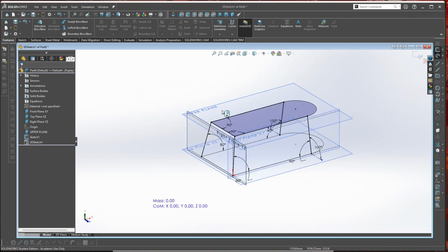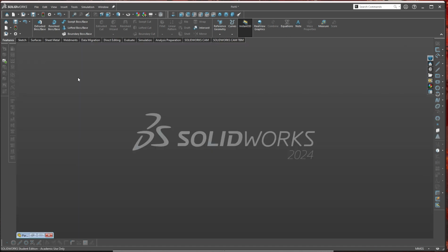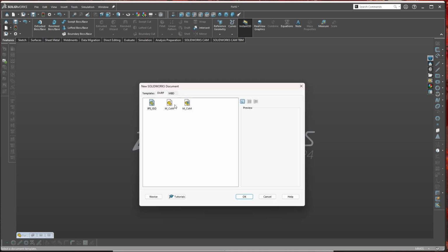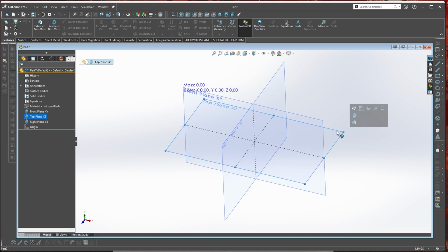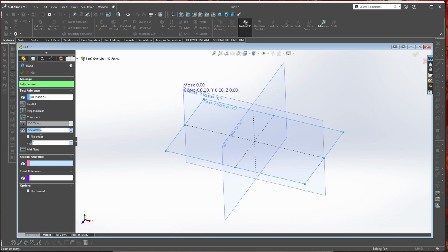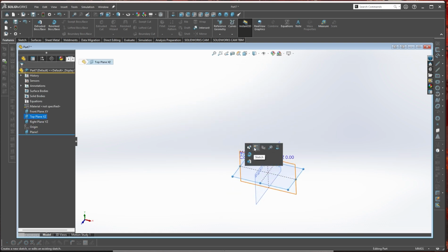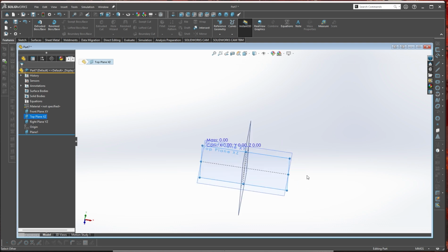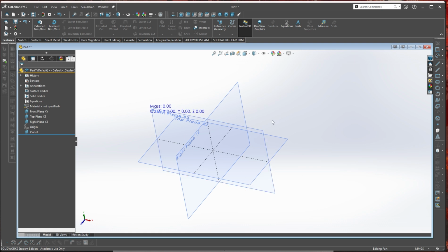So, we're going to set the same thing up, except this time we're going to approach it a little bit differently by using planes. So, when in doubt, plane it out. So here we go again, same exact process. We need that top plane first, so let's go ahead and create that. Everything's already plugged in because I used it last time. There's the 700. We're going to start exactly the same, except we're going to create construction lines, because construction lines are our friends, as always.